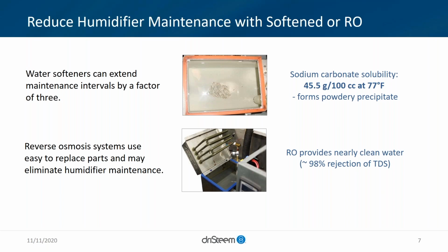So if we talk about applications outside of humidifiers, like steam boilers, for example, they might do a couple different methods of treatment. One of them most commonly is softeners in commercial buildings. So if they're doing softeners, they're also doing other chemical treatments to maintain different solubilities and protect that piece of equipment.